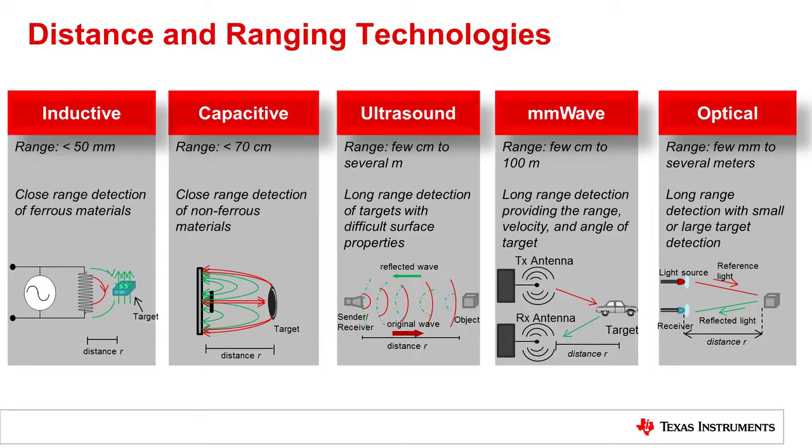Like inductive, capacitive sensing uses the oscillator, but is linked to two conduction plates positioned to operate like an open capacitor. As the targets enter the electric field, the capacitance of the two plates increases, causing the oscillator's amplitude to change, just as in inductive sensing.